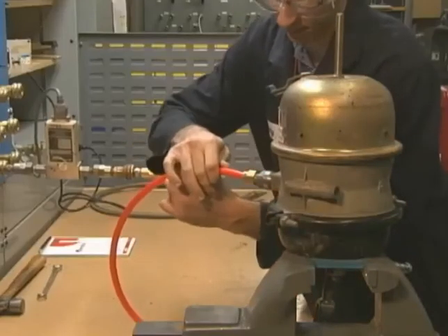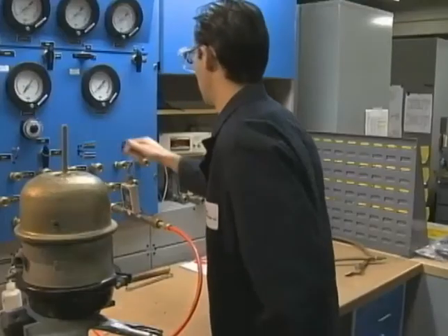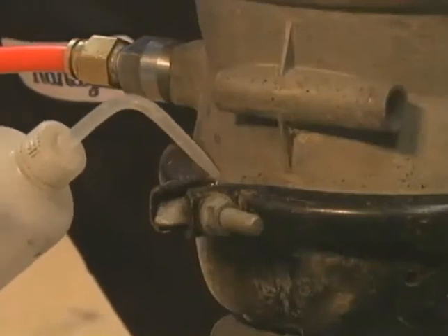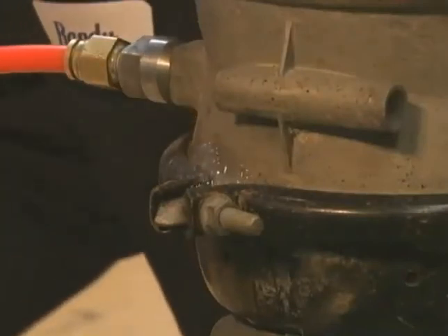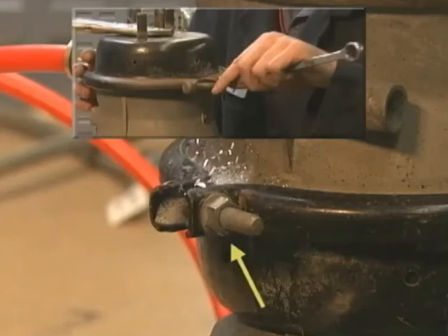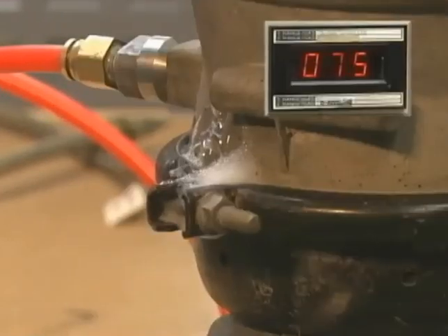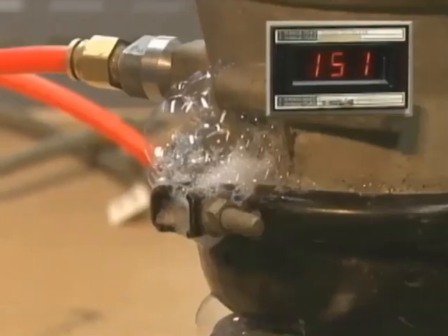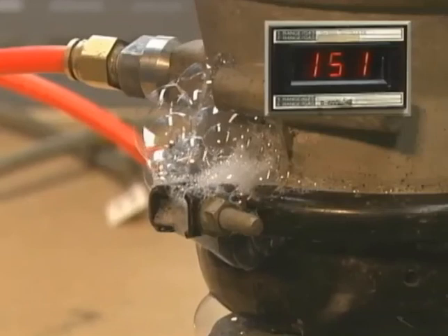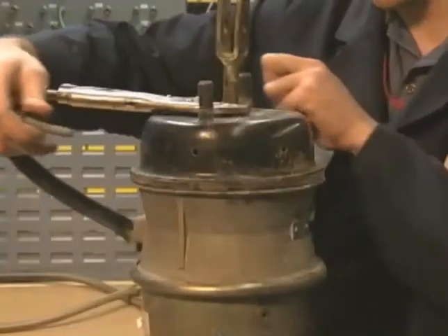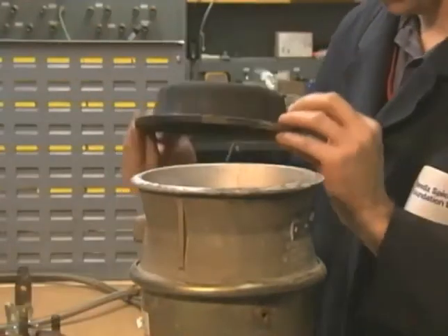When checking for leaks, be sure to include the vehicle's brake chambers and spring brake chambers. Check with a soap solution, and remember that minor leaks may be repaired simply by tightening the nut and bolt at the service diaphragm up to the torque spec published in the service data sheet. For Bendix brake actuators, leakage below 100 SCCM is acceptable. If you encounter a brake chamber that is leaking above 100 SCCM from around the service clamp band, replace the diaphragm and clean all parts.